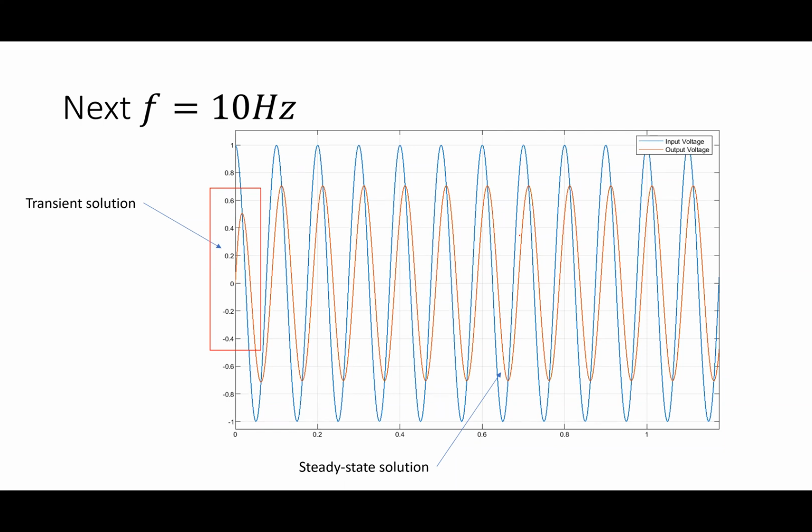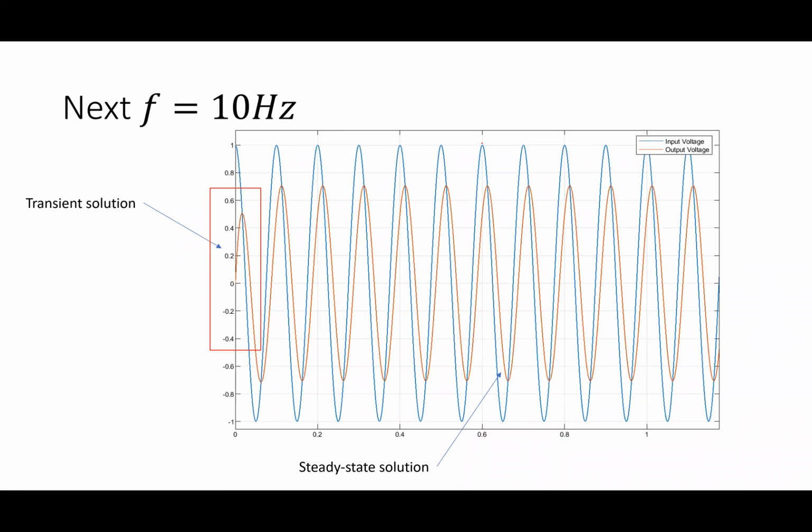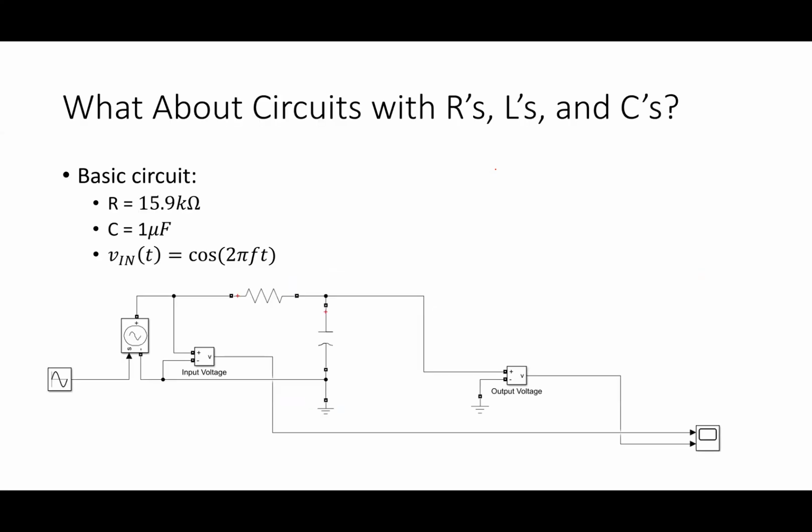All right. Now, if you look at the steady state, once the transient's dead, what's the difference here? If you look at when I had a purely resistive circuit, and I'm going to wrap up here in a minute, this is the input voltage. This is the output voltage. Look at that relationship versus the input and output voltage once I have a capacitor. So here's the peak value of the voltage of the input. Here's the voltage at the output. What looks different in this case? The amplitude is less, and it's shifted, right? The amplitude's different, but it's shifted. That shift happened because of the capacitor.